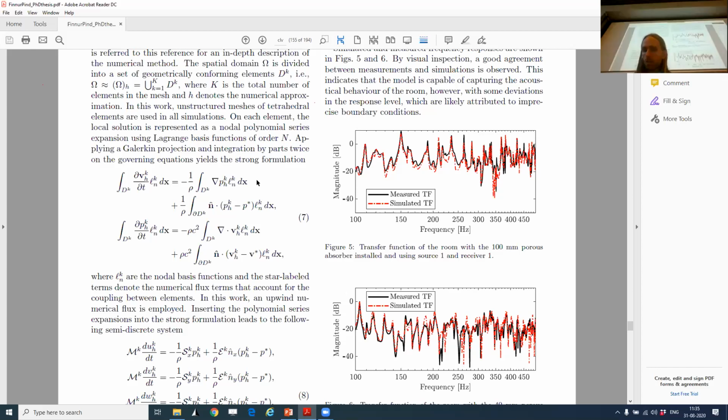Okay, yeah, I agree. I think these results look pretty good, but we have to be a bit careful when we look only at the results in the frequency domain. By the eyeball norm these graphs look pretty good, but actually the reverberation times might not be so great in all the octave bands.